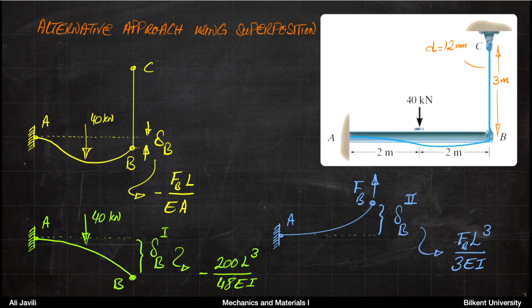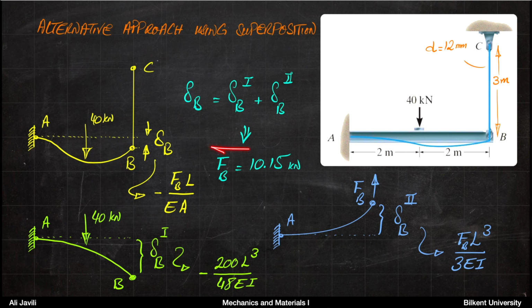So basically, all you need to do now is to say delta at point B, which is the change of the length of the rod, is the deflection of B from system 1 plus deflection of B from system 2. If you do that, in one step you can calculate your FB to be 10.15 kilonewton.